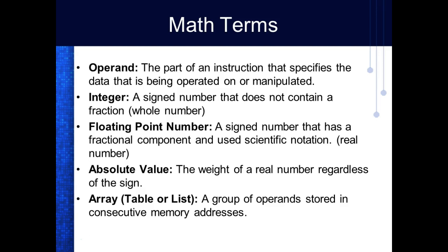So this is what happens on our PLC when it uses signed numbers. If you exceed the range, then you lose the sign. So we probably noticed that when we were counting with our counters, even though it went up past the range of signed numbers, the counter kept counting. But what we end up with is an unsigned number out of that. But we get an indication. Y'all remember what the indication is if you exceed the range?